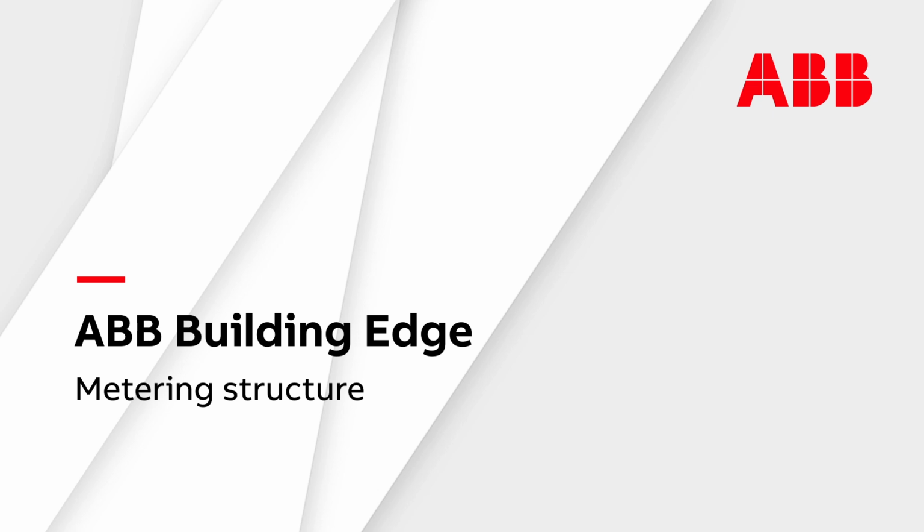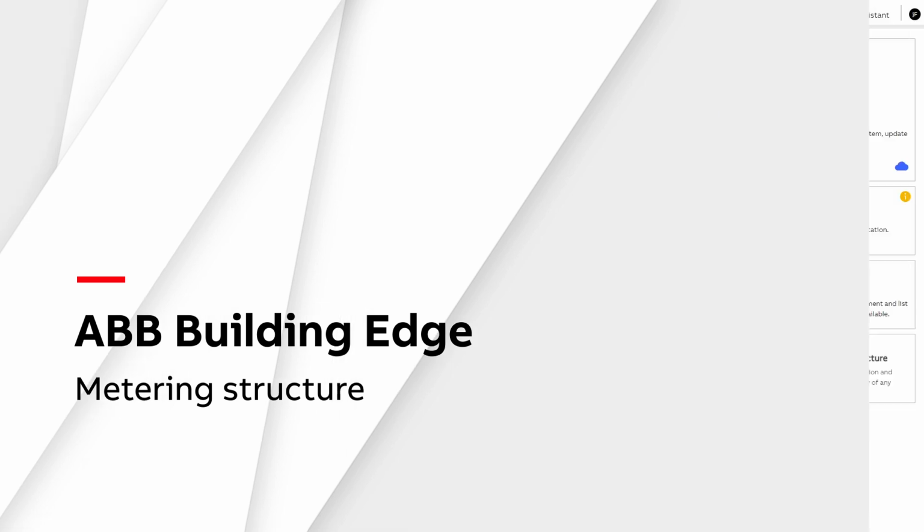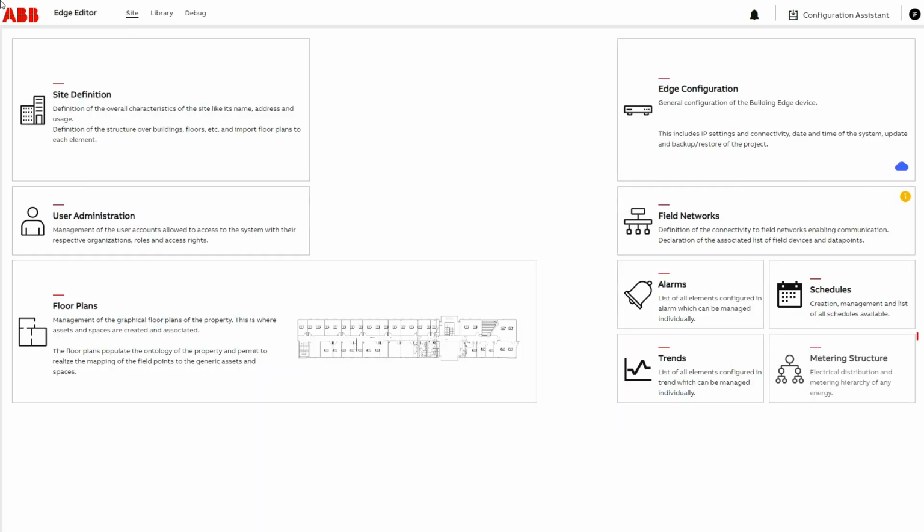Welcome to this video about ABB Building Edge. In this video, we will look at defining the metering structure. Under Site in the top menu, click Metering Structure.